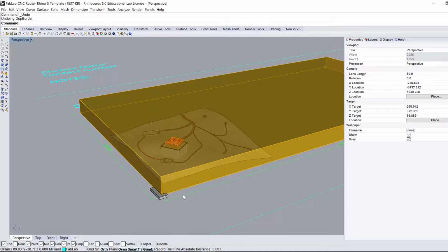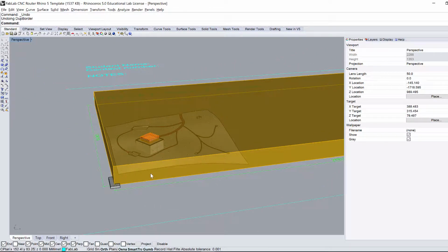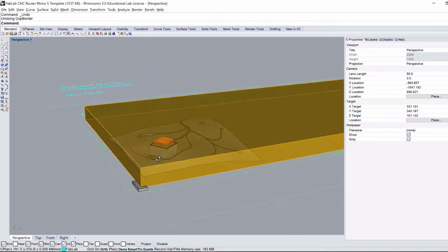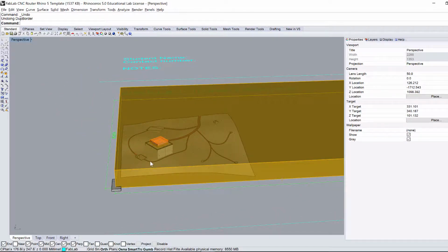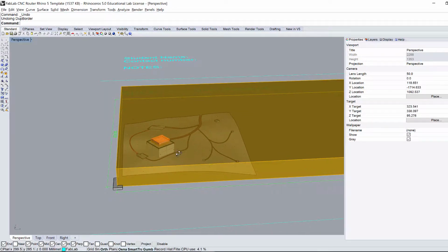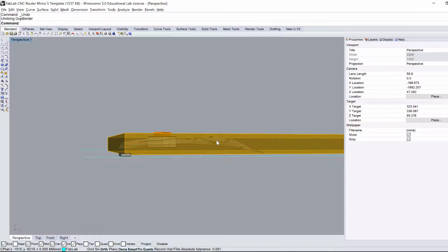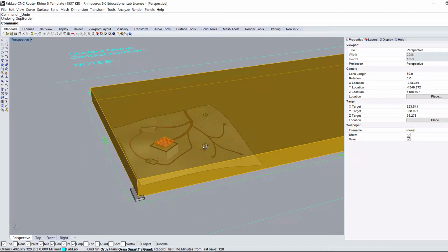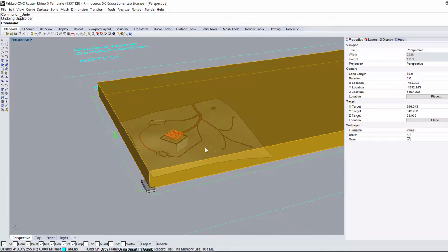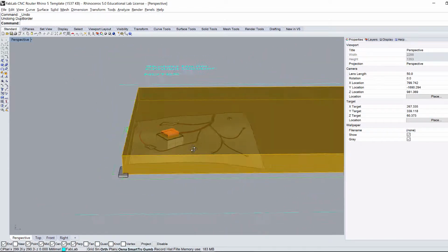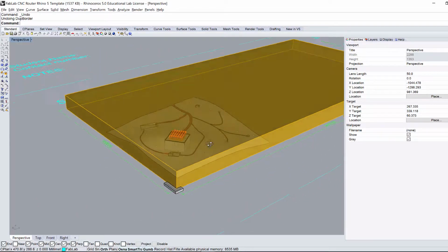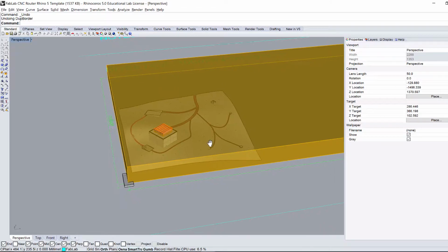Most of the milling time on this model will be dedicated to carving this terrain surface accurately. This will be undertaken using a 3-axis toolpath known as parallel finishing, which was discussed earlier. However, before this occurs, there is a fair amount of excess material that needs to be removed before we can apply this toolpath.